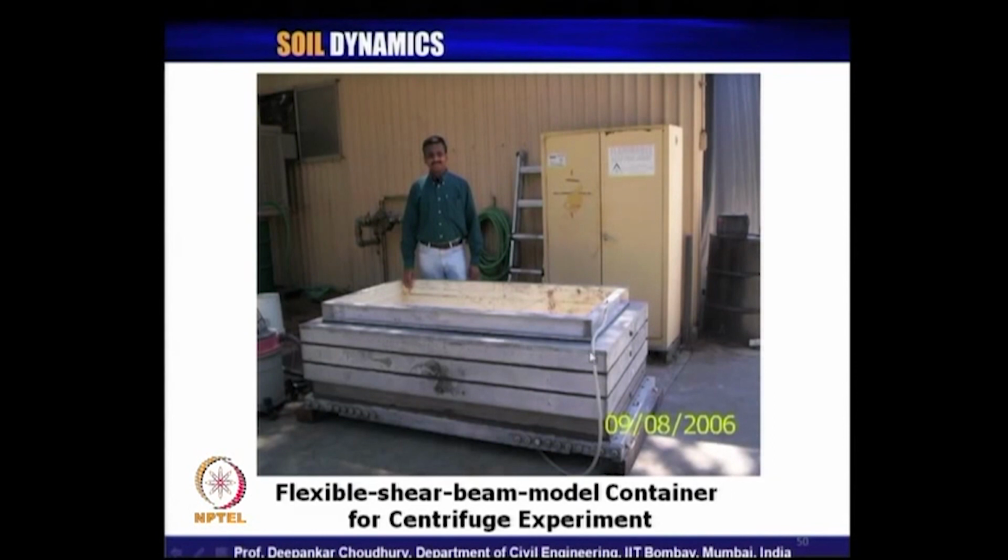So, that is why your model container cannot be stiff or rigid continuously, but it has to be sliced like this using the concept of the flexible shear beam model, and the soil material is kept here. So, that way the dynamic centrifuge testing is done.